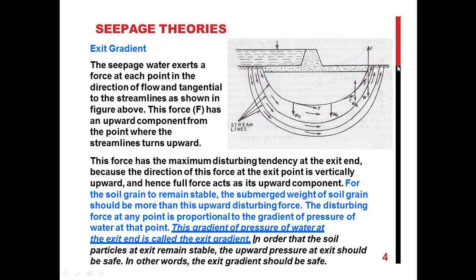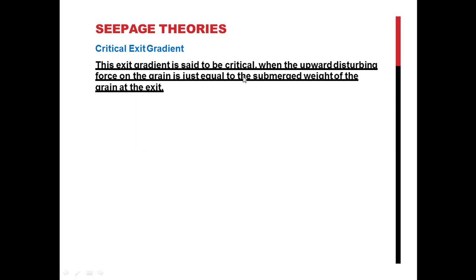This is the exit gradient. When the upward force equals the submerged weight of the particle at this exit point, in that condition the exit gradient is said to be critical. And this is the end of today's lecture.